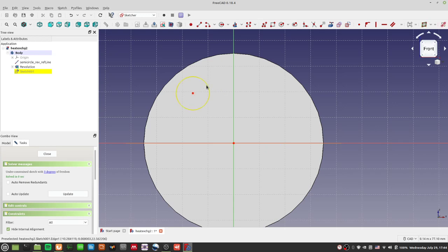I can shift it around. First, I want to control the radius or diameter of this circle. When do I do that? Again, we need to apply another constraint. So click the circle, go to the constraint toolbox, and that's where you'll find all your perpendicular constraint and so on.